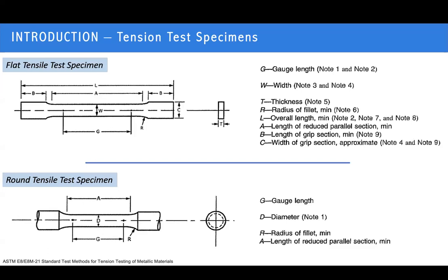When we calculate strain, the length and the area at this gauge length are very important for the calculation of the strains. The gauge length is very important to know, because we need to measure the gauge length before the test, and measure it again after the test, and then we can see what the elongation is, and what the reduction in area is. These things can be calculated.